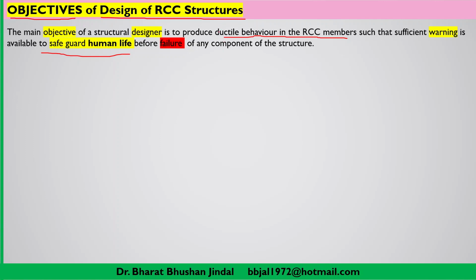But if the member is truly ductile, then what will happen? When it is subjected to loading, it will start bending. And when there is bending, that means before failure of any structural component, it will give us a lot of warning. That means just on viewing that structure, you are able to understand that later on it is going to fail. So failure can be avoided. So when you are going to design a structure, its behavior should be ductile behavior, which will give a sufficient warning sign.